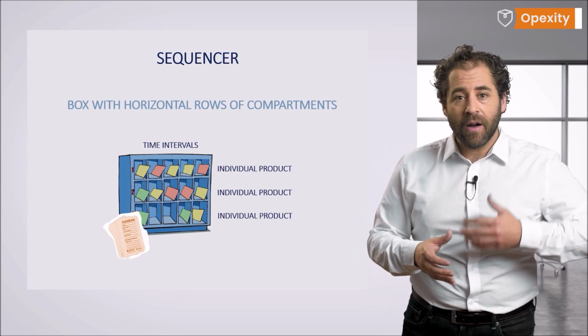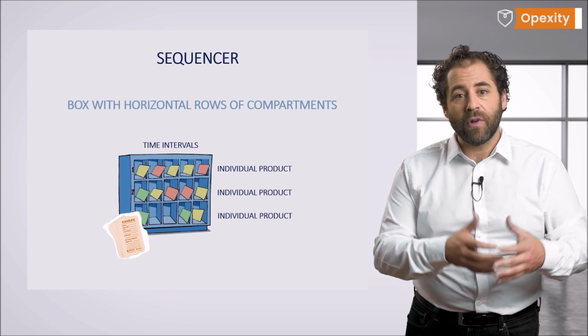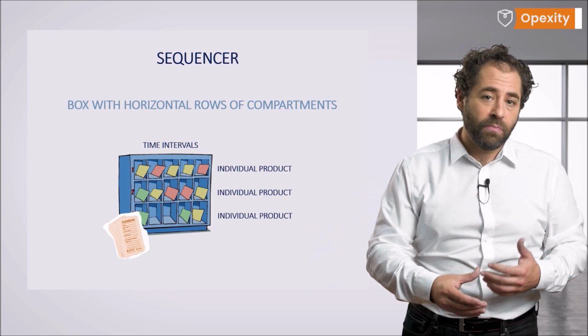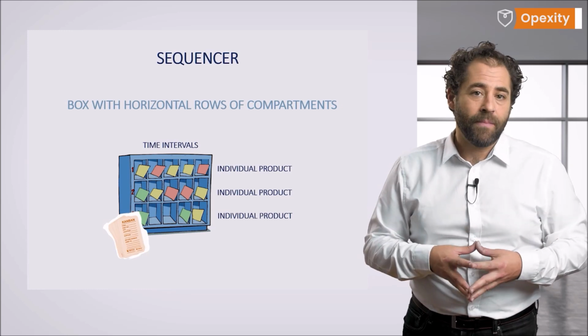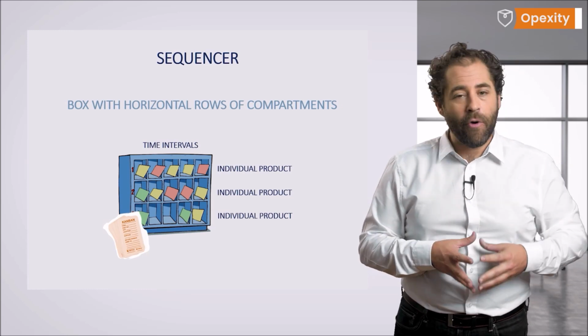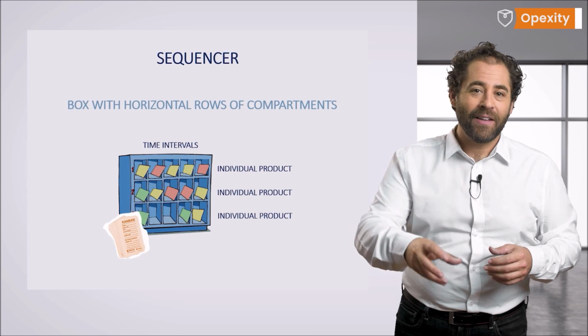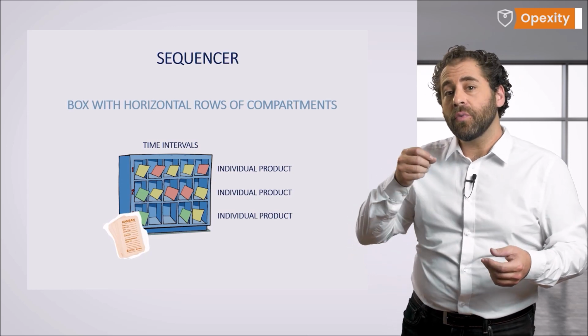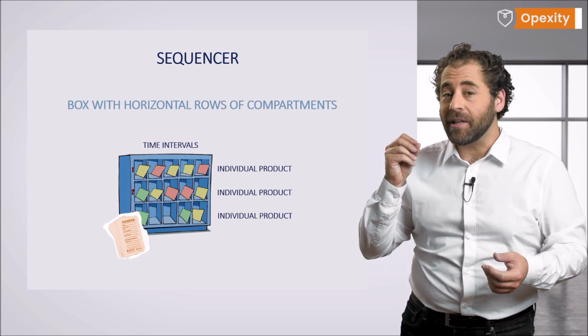compartment, Kanban cards are collected by the transport worker every 30 minutes and delivered to a process that stimulates production in the value stream, usually the assembly area. The cards are added in order to present the production sequence and are removed when production is completed.